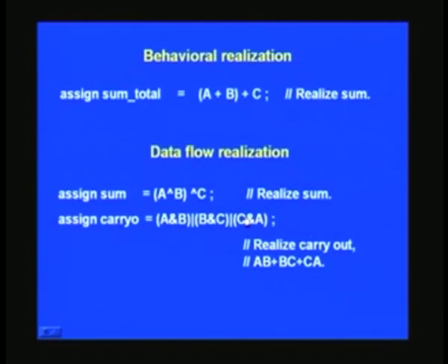So there are three ways of implementation of the same full adder, and one we have already seen at the earlier stage, that is the behavioral level of realization. Suppose you can just put a simple arithmetic expression as such, a plus b and c, and this parenthesis is only to guide the synthesis tool to make it very efficient. If you don't put this, it may infer internally 2 mux and so on. Instead of that, only 1 mux will be put if you guide the synthesis tool as such. That's why this parenthesis. It's a good habit to use parenthesis freely, right?